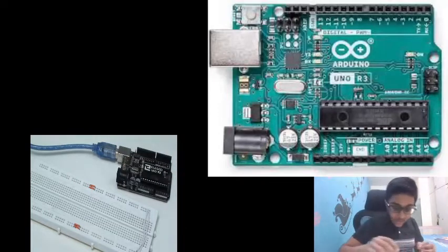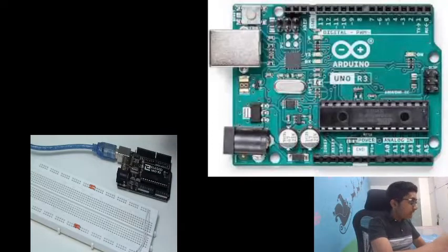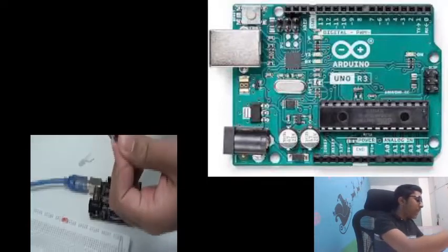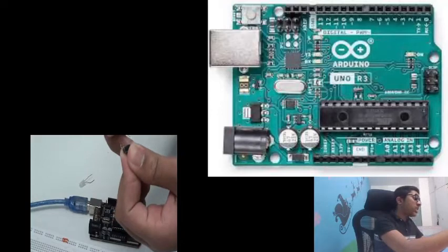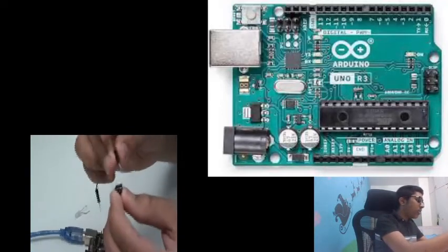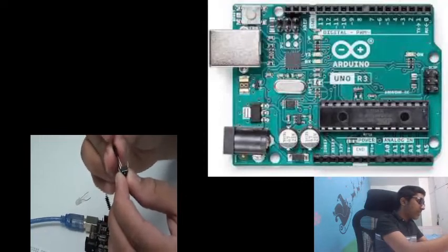So what a push button is basically a momentary switch, right? We press the push button, it can send a 1 signal. We leave the push button, it sends a 0 signal, right? Now if you see, the leads which are bent towards each other are actually connected. So when I press it, a current is going to flow from this lead to this lead, right?